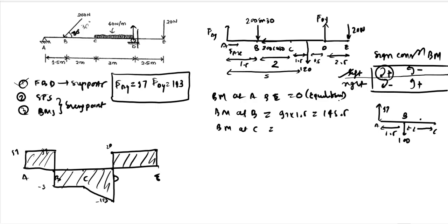You can just cross your beam somewhere here and check the left side forces, and draw the FBD for the left side forces. Just cross your beam somewhere here. Once you make the FBD, it will be easy for you to make the FBDs of other cross sections.